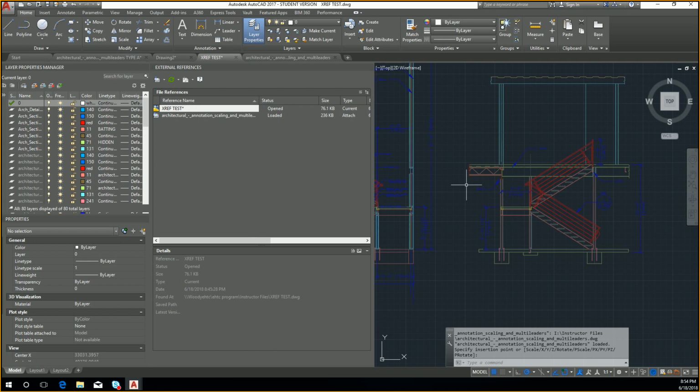So you can do that. Yeah. So you could open up the original block, make modifications, type I in a different drawing, and you would redefine whatever you inserted previously. So this, in this case, would be this drawing here.